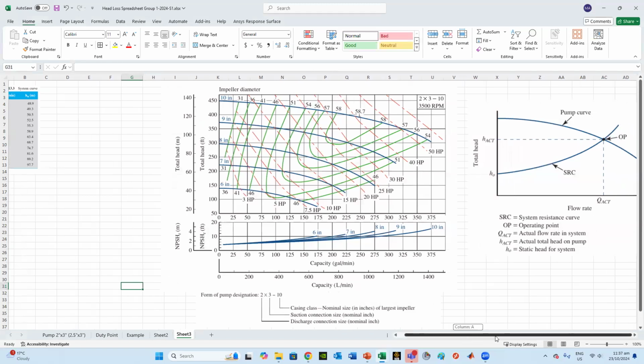But what we're trying to do, based on my H values, applying from 0 up to a certain number, is get this curve, which we call the system resistance curve. And I intersect it with one of the suitable curves for the pumps. I think it's about 9-inch or 8-inch between them. Then I will determine the operating point based on that, and also the one they want me to find. One is the maximum point at which the pump can work with no issues, based on my pump curves and its efficiency. So that's what we're trying to achieve.